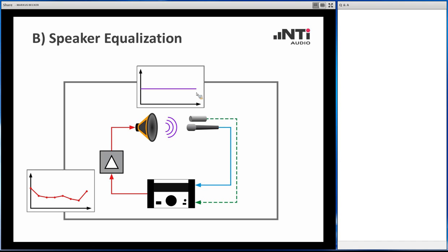This looks simpler than it is. Keep in mind, this is a bit of a demanding procedure, but it is feasible if you have high quality devices in your setup. And now we can, of course, directly measure the frequency response from our microphone here, the one we want to test, and we get the same response as in the setup before, but now we get it directly with a direct measurement due to this linearized, equalized frequency response from the reference speaker.